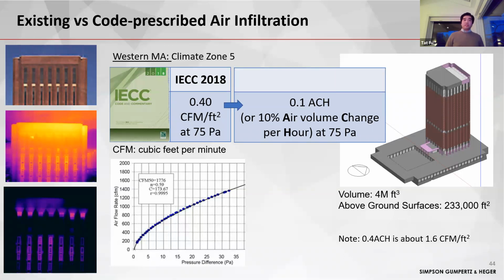But what's interesting is you can see that the middle windows are a brighter color compared to the other windows, even though they probably should have the same thermal bridge. One of the reasons could be that for the middle 2 windows, the wear and tear is greater on the air leakage part, and they are actually leaking more air compared to the windows on the 2 sides.